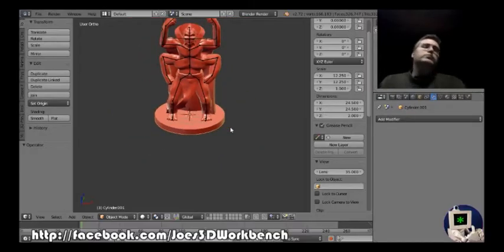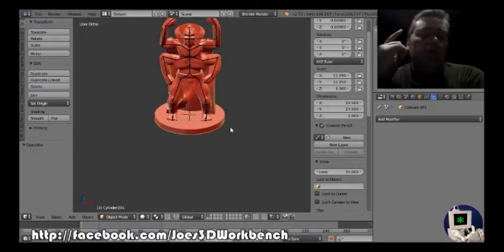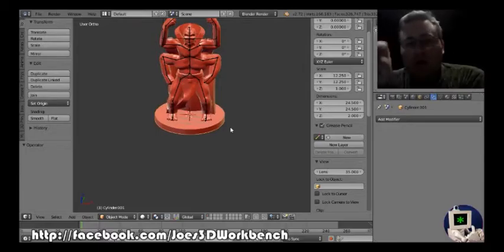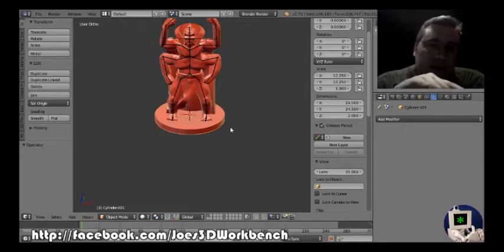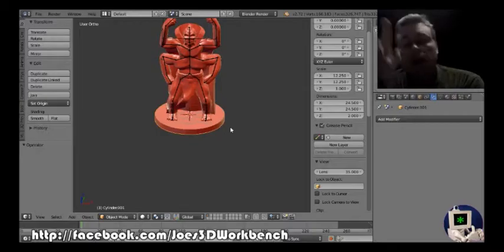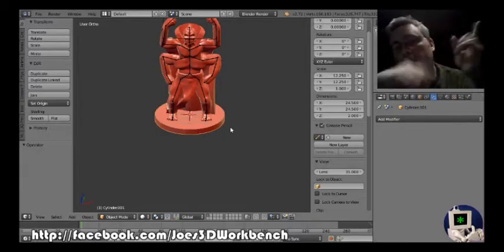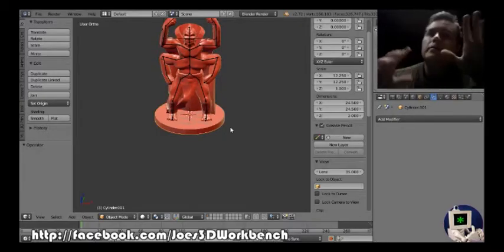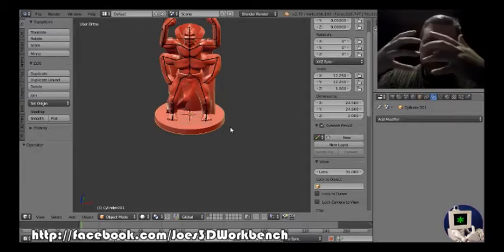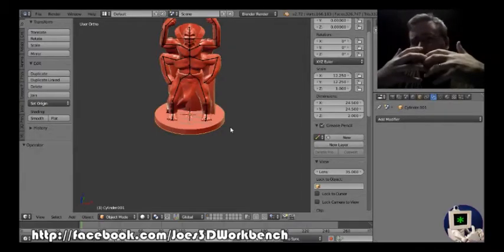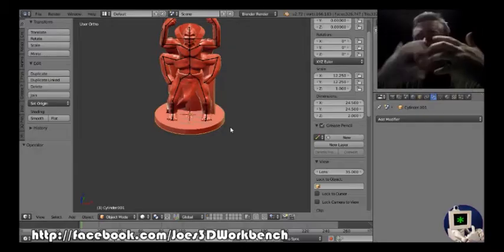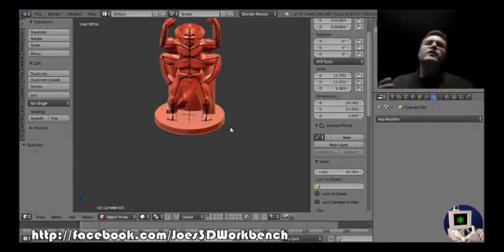This is what we need to do. We need to Boolean all of these together. But we also want the poly count to be lower. So we need to decimate and then Boolean. If you Boolean them together and then try to run the decimate modifier, what's going to happen is where high geometry meets high geometry but isn't quite set on correctly, it creates new geometry in between, and the decimate modifier is going to have a hard time picking that out, and the Boolean modifier is going to have a hard time putting it together.